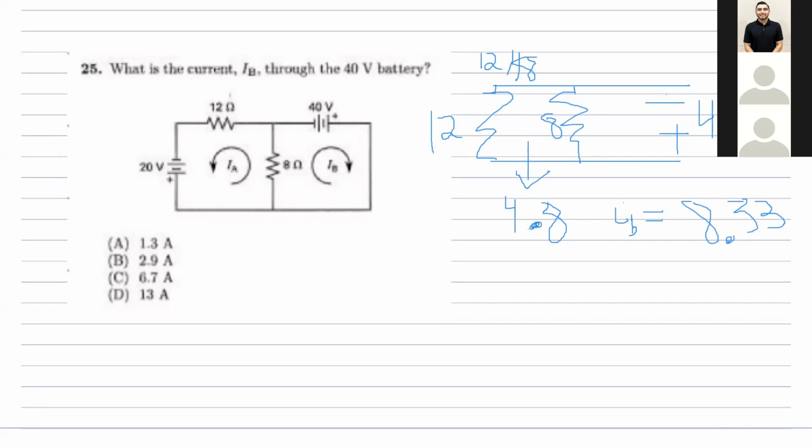All right. So now we kill this source right here. That's gone. So now we're just shorting this 8 ohms, right? So it's going to look like minus, plus 20, and that's 12. This one gets shorted right here, right? By this path. You can kind of just ignore it.